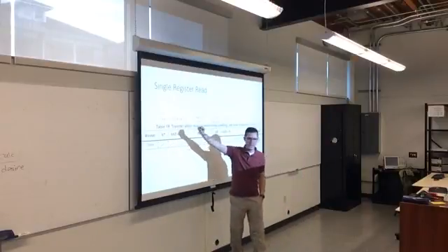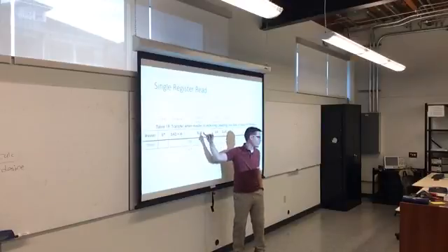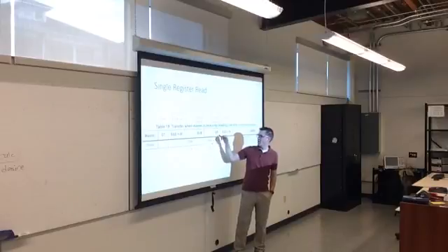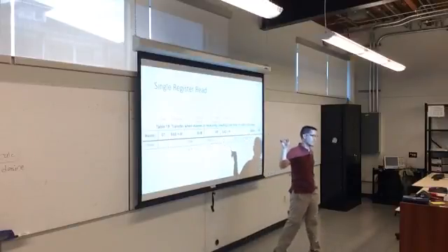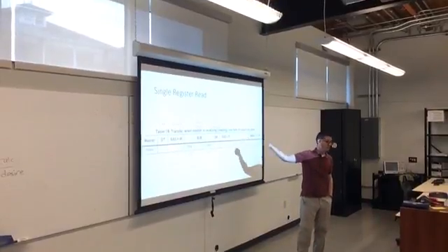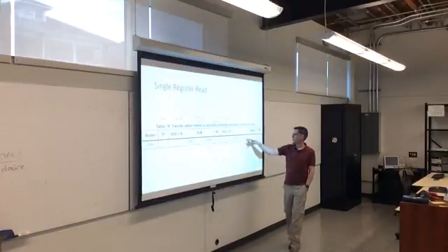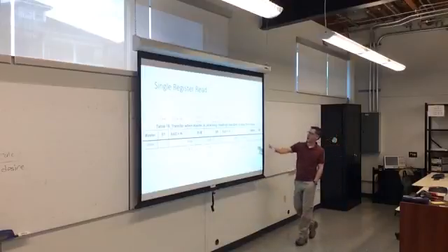The SR means repeated start. So you don't say stop here. You say start. It'll do a repeated start, and then you'll read from it, and it'll give you the data back. And once you get the data back from it, you can NACK the transaction and say you're done. If you acknowledge it, it may keep giving you more data if you have the multi-byte operation on.